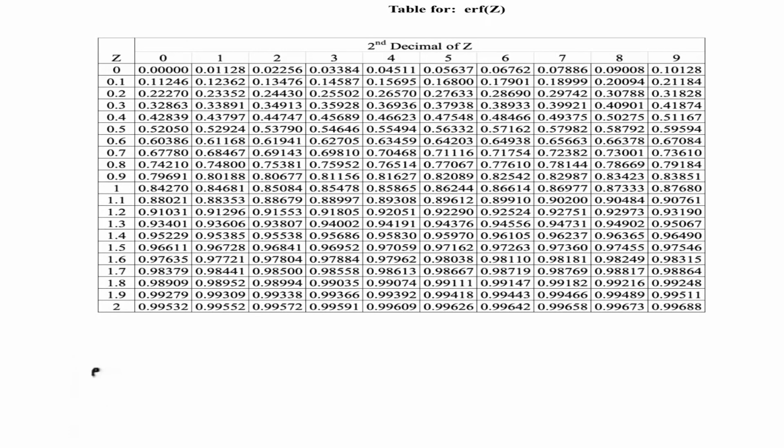Now, we need to find out z such that error function z is equal to 0.64516. Exactly this value may not appear in the table, but we can assume a linear relation within the small range of z. Okay. So, let us see one value which comes before 0.64516 and the other which is slightly greater than 0.64516. From this table, we have 0.64203 and 0.64938. This corresponds to 0.65 and 0.66.